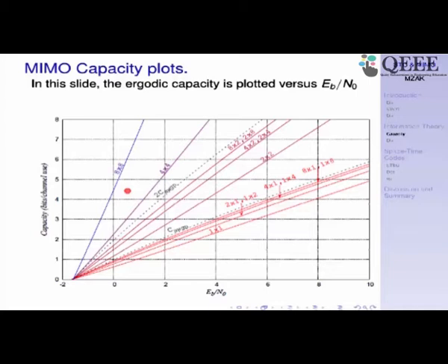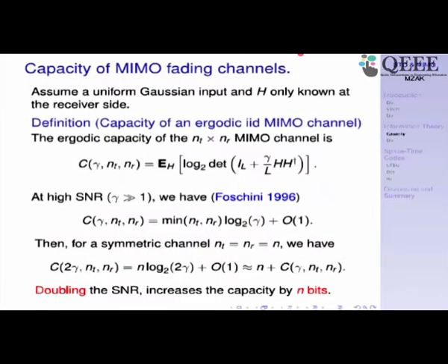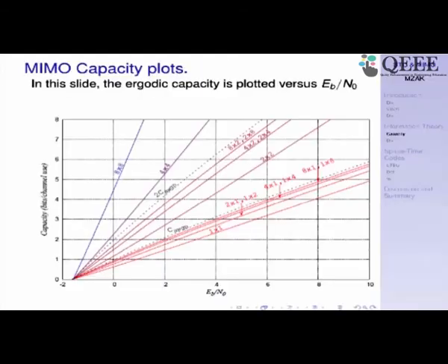That's why MIMO is going to be in all the future standards, because to support high throughputs, this is the only way forward. But remember, what we have derived is the ergodic capacity, the capacity when the channel is changing every instant. It is not block fading like in the typical channel. It is for a channel that is fading fast, varying every channel use. So for one time you transmit something, in the next interval the channel has changed. So that is an ergodic channel. But that's not the practical case. The practical case is for a fixed duration. We'll go to that in a moment.